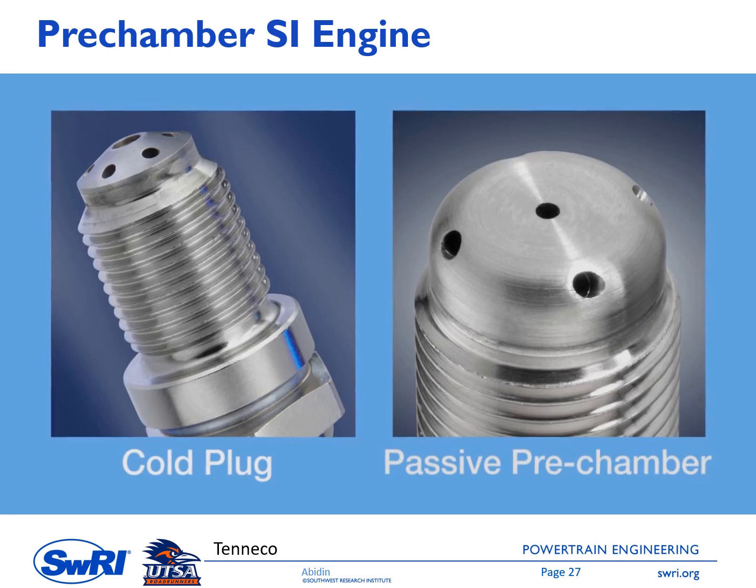Passive pre-chamber usually is good for full load operating conditions, especially if you drive your car at high speed, so drive your car through I-410 or I-35. If you use this passive pre-chamber, then you will gain some efficiency. But it has some drawbacks when operating the engine at part load, because at some point you might have a misfire when using this pre-chamber. So this pre-chamber is one of the hot topics right now. I know one of my team is doing research on designing a pre-chamber to be able to operate under part load and full load operating conditions.